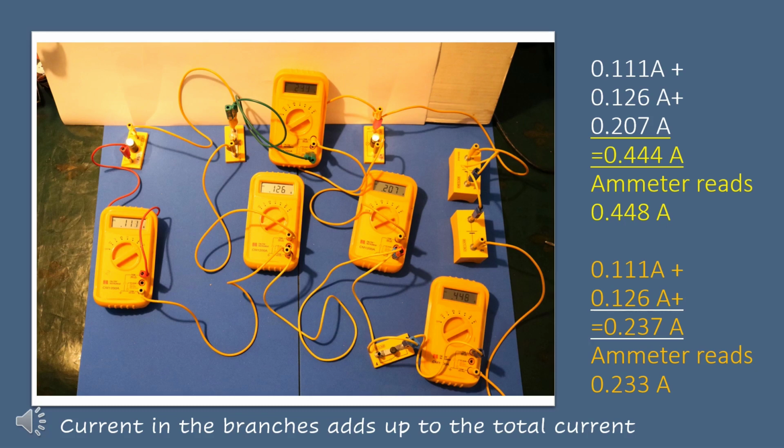Another photo here to show you. This time I've added in that extra meter. So that's like, if you remember, the counter 5, counting the lorries that go past Aldi stores and Sandu stores. So first let's have a look at the 3 meter readings down each of the branches. So that's like the Tesco reading, the Aldi reading, and the Sandu stores all added together. Well, that gives us 0.111 amp plus 0.126 amps plus 0.207 amps, which gives a total of 0.444 amps. And our ammeter reading, if you can see on the bottom right hand corner, reads 0.448 amps, and that's good enough for me.